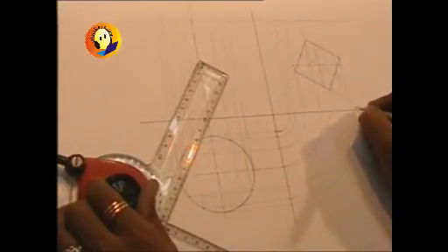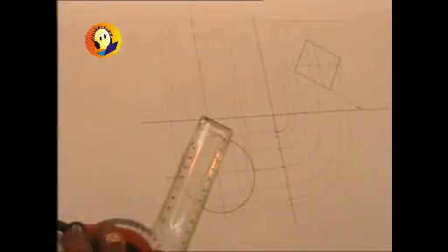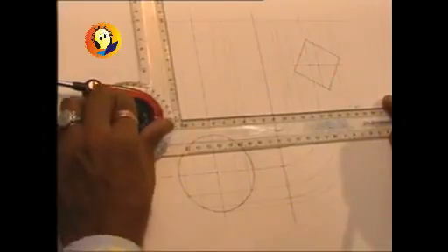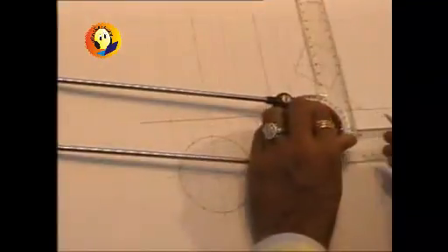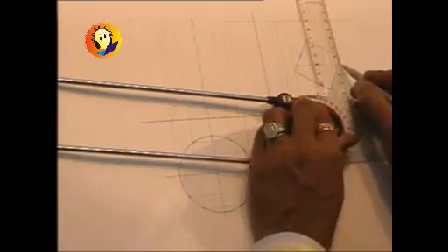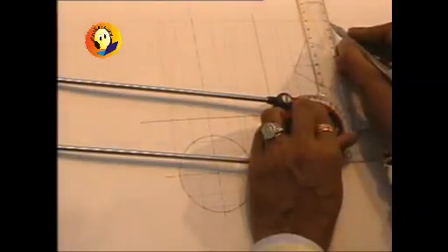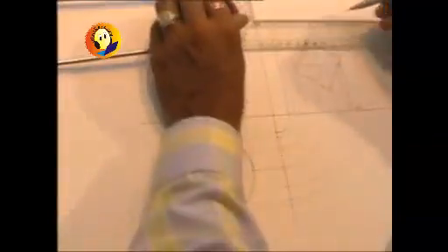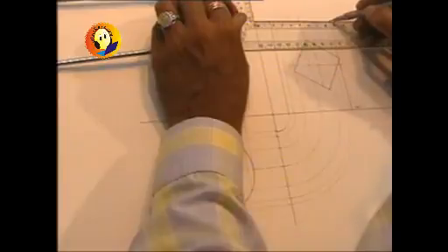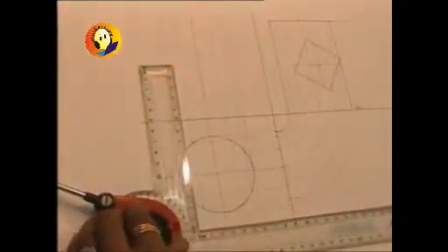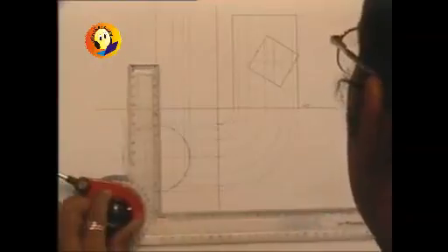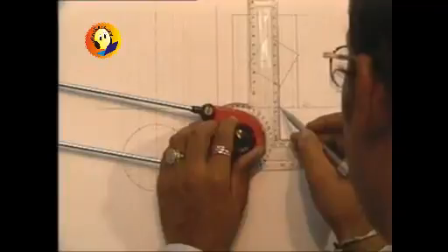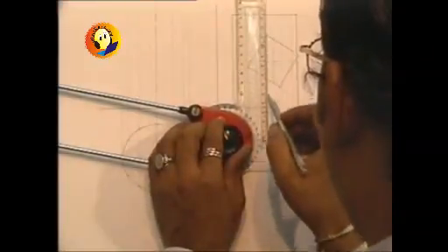The distance between the axis of the cylinder and axis of the square prism or square hole is given to us as 10 millimeters, and it is in front of the axis of the cylinder. So in the side view everything is shown, so I can darken the side view. And now these 4 points of the square are to be taken to the top view. So we will have to draw projectors through each of the corners.